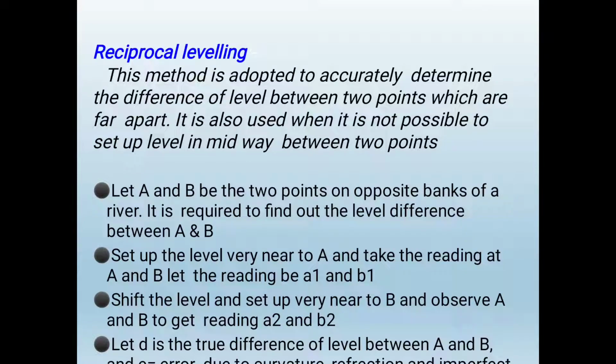Reciprocal leveling. This method is adopted to accurately determine the difference of level between two points which are far apart. It is also used when it is not possible to set up the level midway between two points.